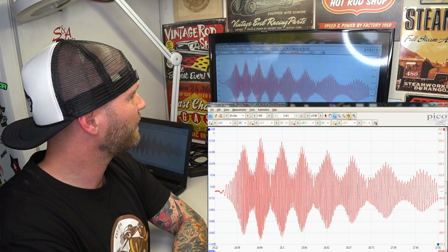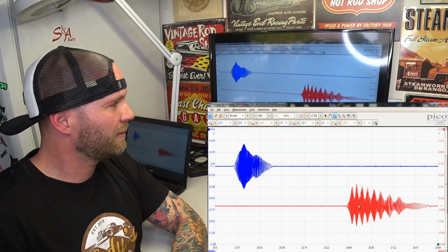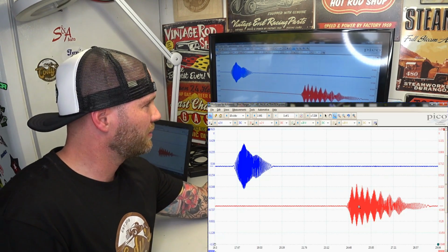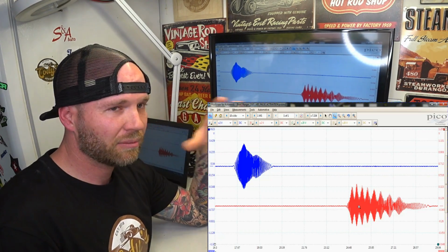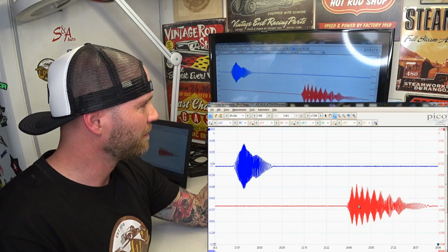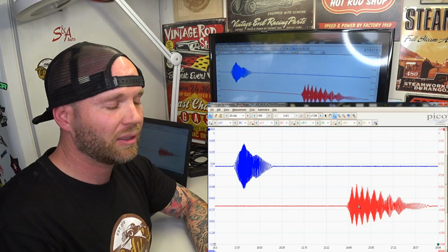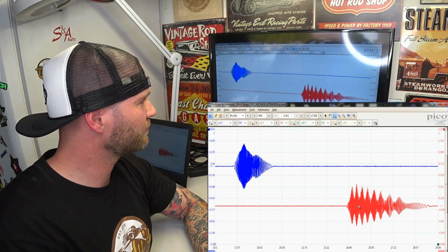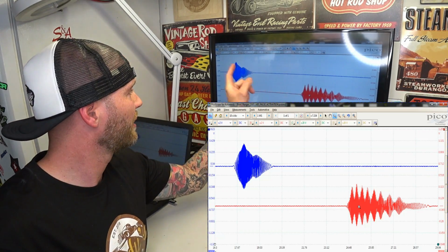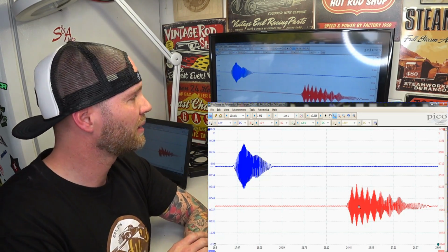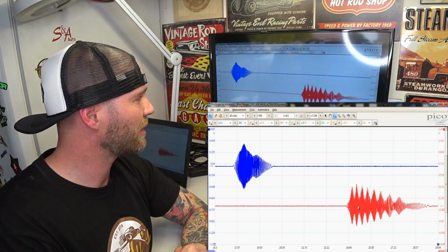If that electronic brake control module is seeing that, it's saying that this wheel is spinning a whole lot differently than this wheel right here. So it's going to apply the ABS, because they're not matching. It thinks that wheel is spinning differently than this wheel. So it applied the ABS, and that is the false activation that I was getting on this test drive.